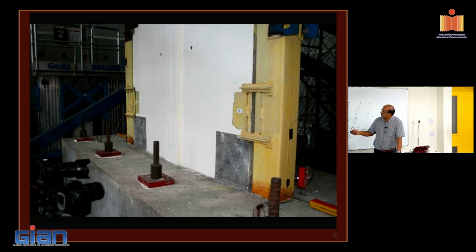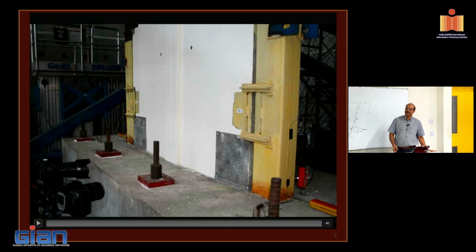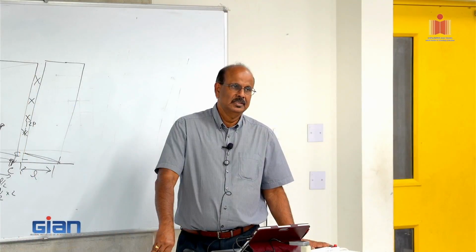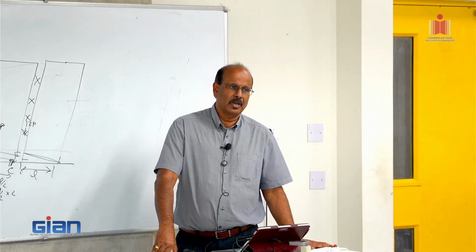This O-ring is attached with a weld here and a weld here. You just remove the weld and the O-ring comes out, and you put in a new O-ring and weld it together. It's easy. Even if this was a concrete column, you can put an embedded plate and then do the same. We actually tested it with the concrete column also. It works really well.